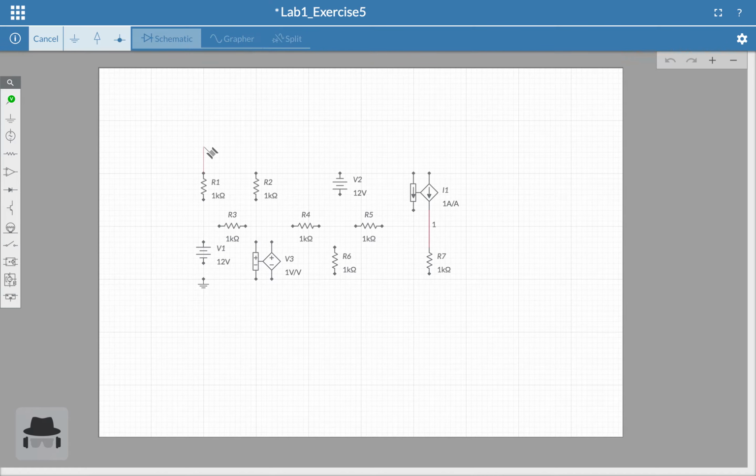We'll go ahead and connect this top. And it's going to go to the 6-volt source. And every time you connect a wire, you should see a little dot appear there. If you don't see a dot, the wires aren't connected. And sometimes that happens, and then you don't see the dot, and then you'll get the wrong value. So it's important to make sure that you get the right value.